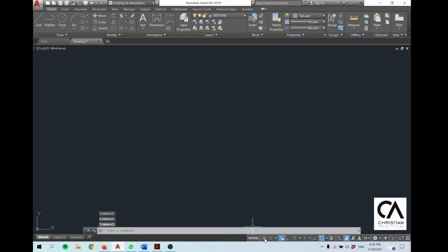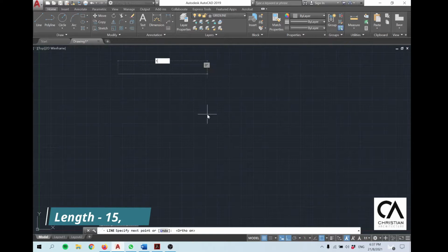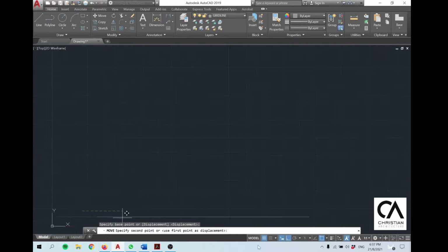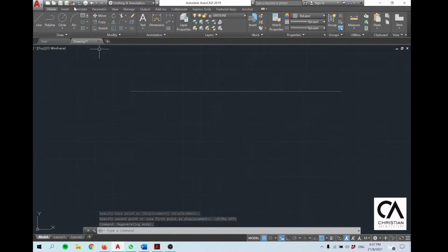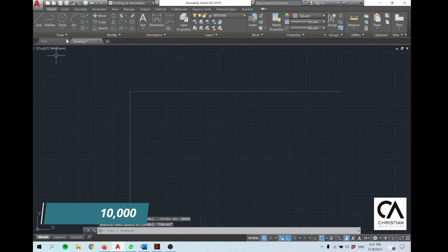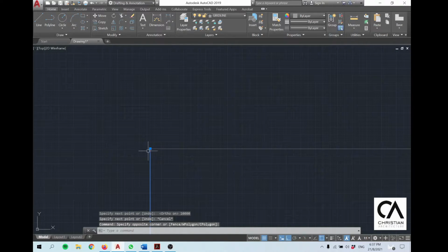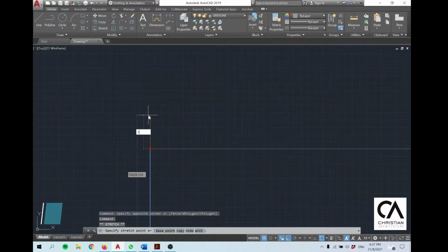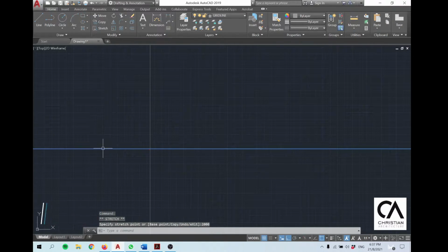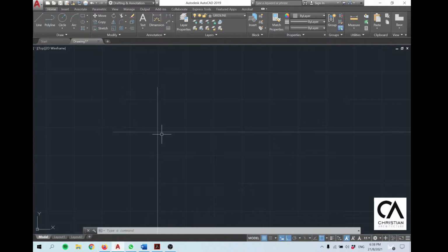And then I will turn on the grid mode, and then the first line you need to do is the horizontal line. And then the next one, then you click this line. You see there's a blue square, so you just left click and then move your mouse to the top and then type in 2000. Same thing on the horizontal. Click the blue square and then 2000, enter. As you can see, there is an intersection, so you will need to keep it this way.